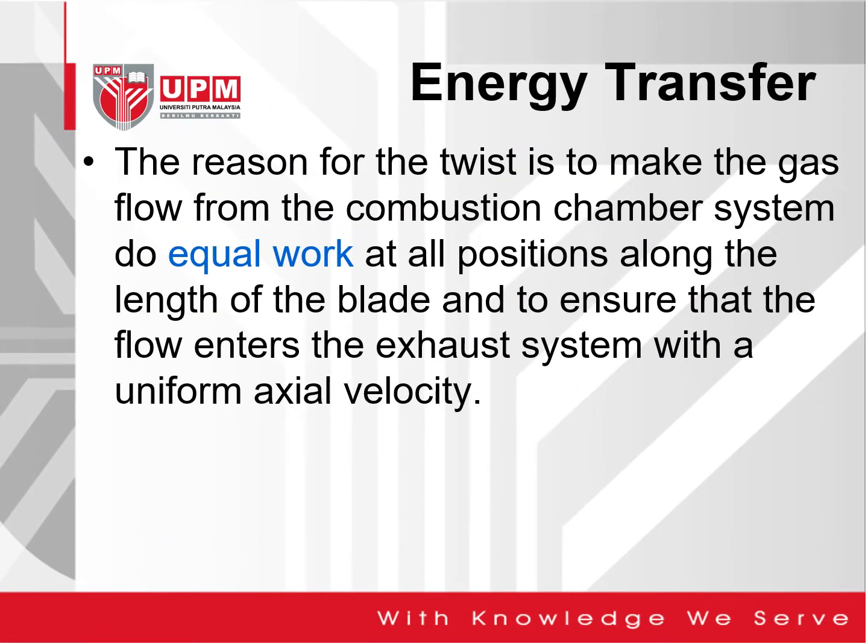The reason for the twist is to make the gas flow from the combustion chamber system do equal work at all positions along the length of the blade, and to ensure that the flow enters the exhaust system with a uniform axial velocity.